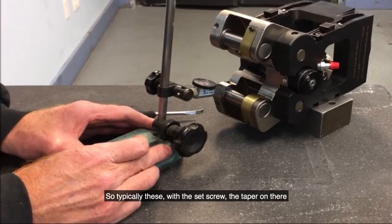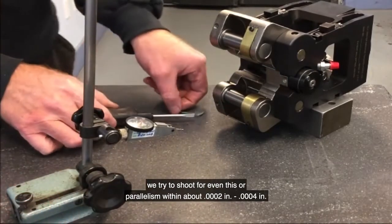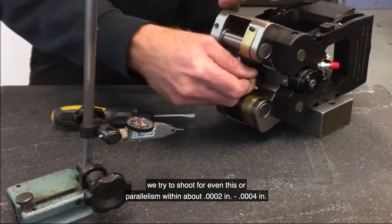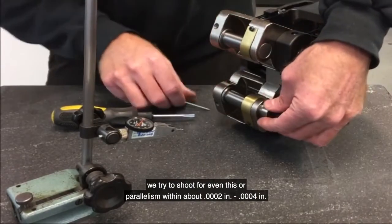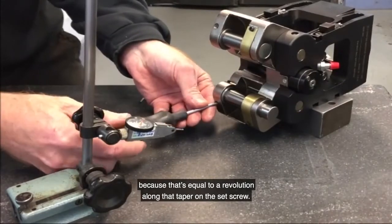So typically with these set screws, with the taper on there, we try to shoot for evenness or parallelism within about 2 to 4 tenths, because that's equal to a revolution along that taper on the set screw.